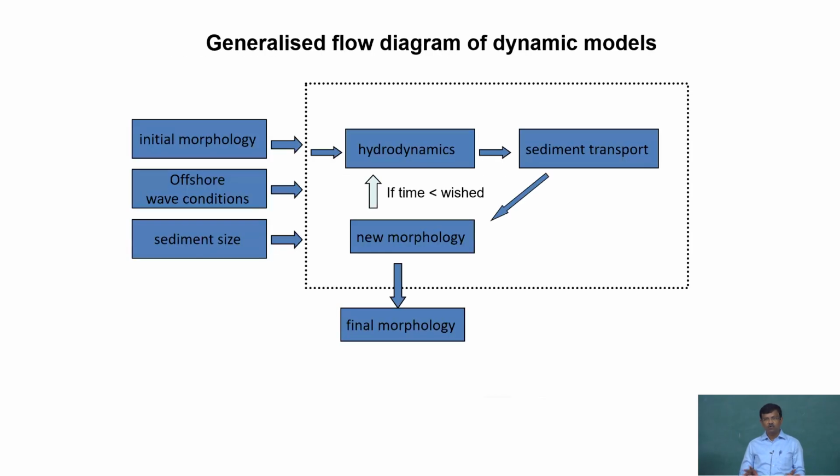Ultimately, if you want to have a very comprehensive look at it, a full dynamic module, you have to integrate your offshore wave to the nearshore wave and hydrodynamics, and the material is with you. The initial morphology is given to you, what material is there is given to you with both waves, and you are driving the sediment transport.